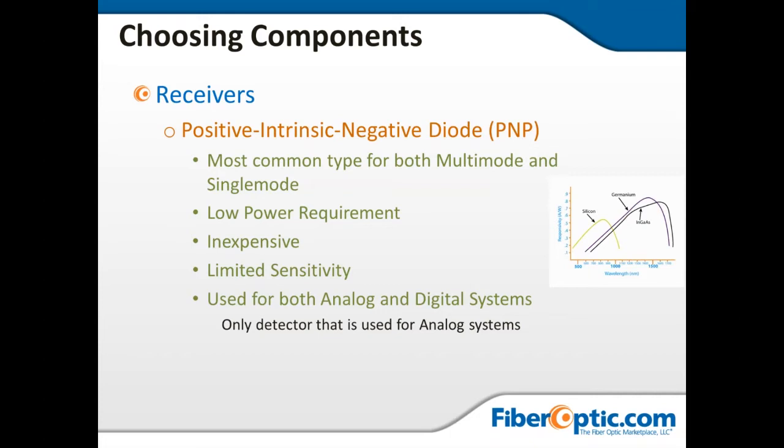Now, the picture you see here is a sensitivity by wavelength and by the receiver's doping of the glass. So you can see in multi-mode wavelengths, it typically had been a silicon type of dope. And then the next generation that operated up around 1310 and 1550 used a germanium-based doping material for the lens itself. And then as we went even faster, beyond the 1550 wavelength, up past 1625, you notice that the response rates on the little graph show that the germanium receiver really fell off in sensitivity as you approached even longer wavelengths beyond 1600 nanometers.